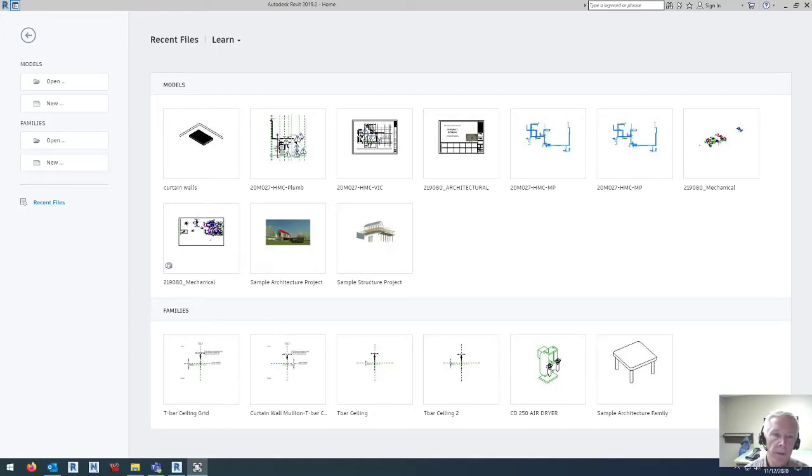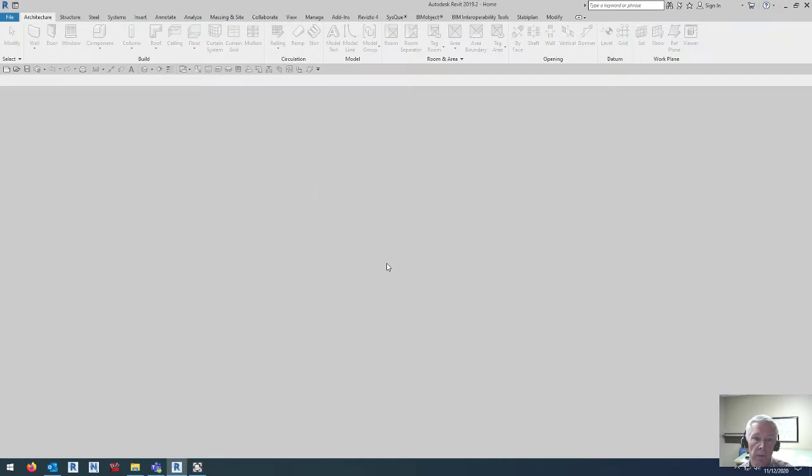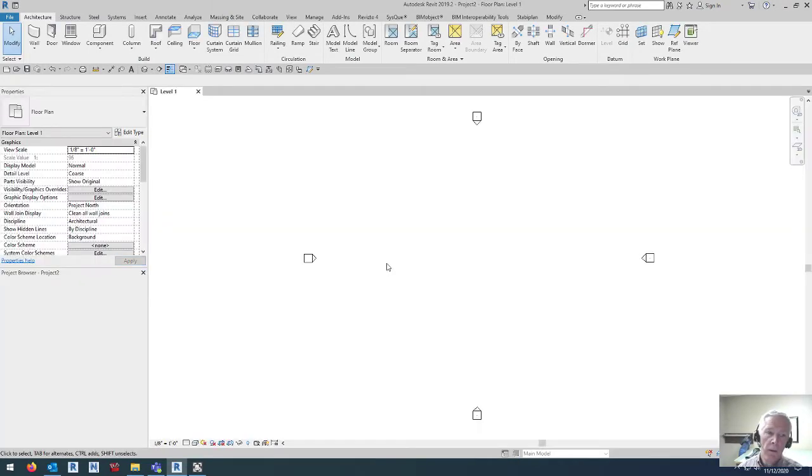In today's video, we're going to learn in Revit how to create a three-dimensional 2x2 lay-in ceiling. So we're going to start with a new project. I'm going to pick architectural. And just to demonstrate, the reason we do this is in 3D modeling, 3D coordination, out of the box Revit ceilings don't show up very well. So what we're going to do, let me get my project browser in here.